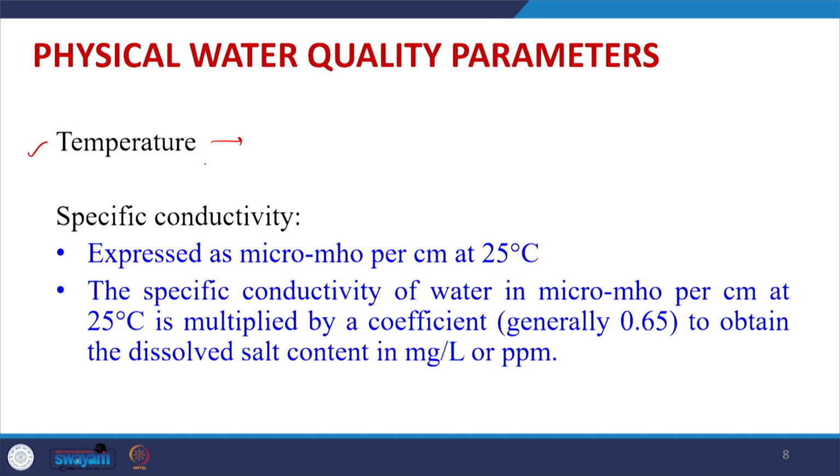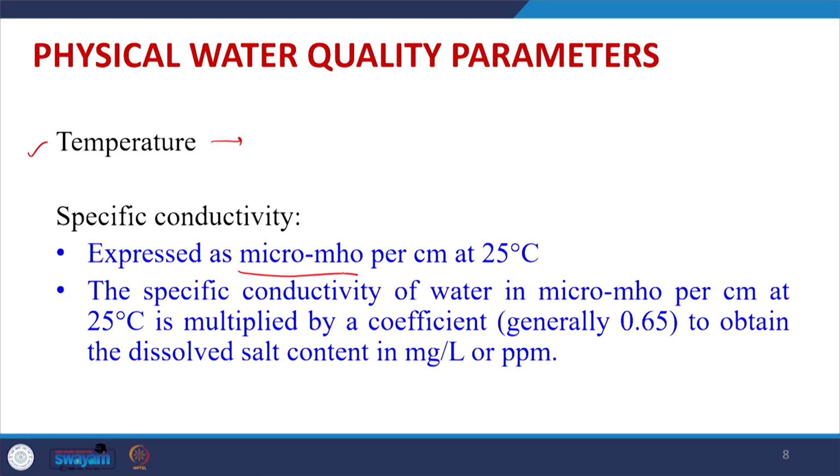Similarly, the temperature of water also affects the specific conductivity of the water. That means if the temperature is changing for the same water, the specific conductivity will also change. So, specific conductivity is expressed as micromho per centimeter at 25 degree centigrade.